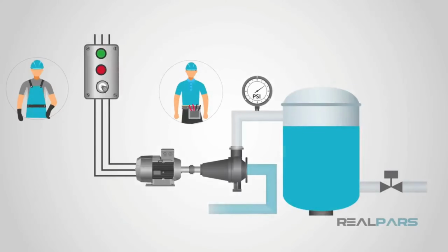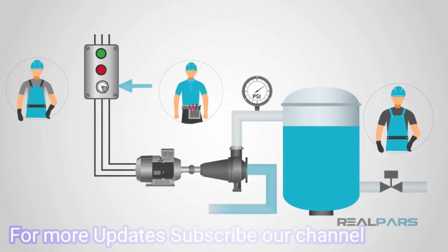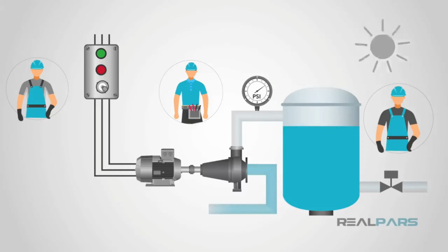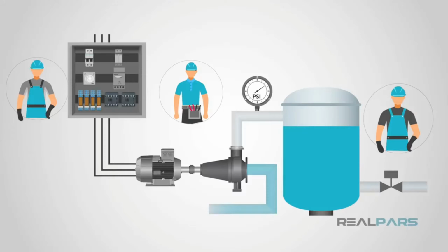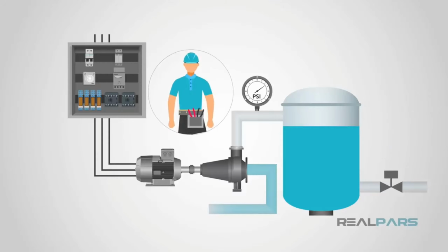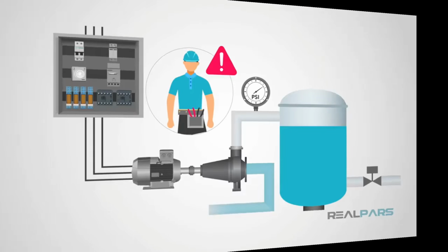Before SCADA, plant personnel had to monitor and control industrial processes via selector switches, push buttons, and dials for analog signals. This meant that plants had to maintain personnel on site during production in order to control the processes. As manufacturing grew and sites became more remote in nature, relays and timers were used to assist in the supervision and control of processes. With these devices employed, fewer plant personnel were required to be on site in order to oversee and control operations. While relays and timers did provide some level of automation, the panels required for these devices took up valuable real estate. Troubleshooting was a nightmare, and reconfiguring was difficult at best. These issues, in conjunction with the need to grow even larger industrial plants, helped to facilitate the birth of automation.